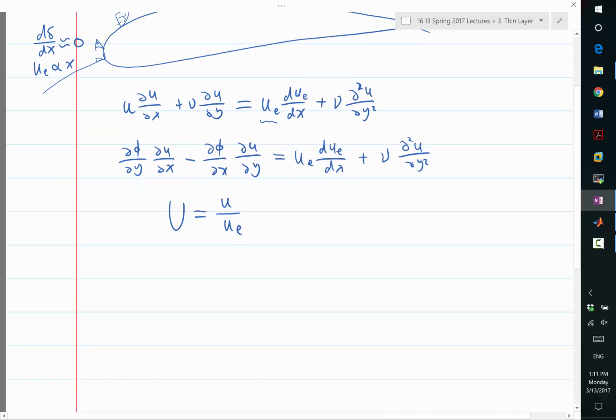And then we know that the length scale in the y direction develops as I advance downstream, right? So we are going to set a certain length scale, let's say delta, being a function of x. In the similarity solutions, we know if we have Blasius, delta x grows like square root of x. That's a length scale in the y direction. In the other Faulkner-Skan equations, delta x grows to some other polynomial, maybe slower than half, maybe greater than half, a certain polynomial power law of x.